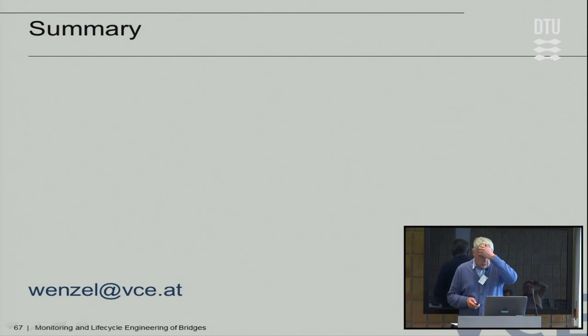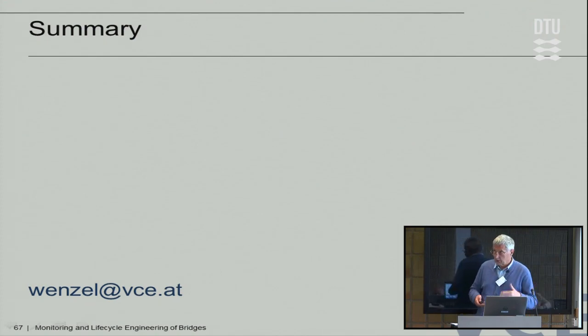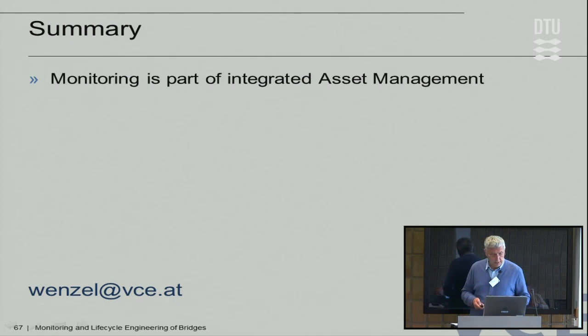So in the end, let me just summarize my opinion. Besides teaching monitoring, I do a lot of consulting work, and this is more the practical issue. Now monitoring becomes more and more part of asset management. We work with ISO 55000 in asset management, and we use the ISO 31000, the risk management framework. We have currently drafted a new Eurocode on risk-based inspection, which is already accepted and will come out. So we have tools that the clients can use, particularly in, let's say, changing the frequency of their inspections.